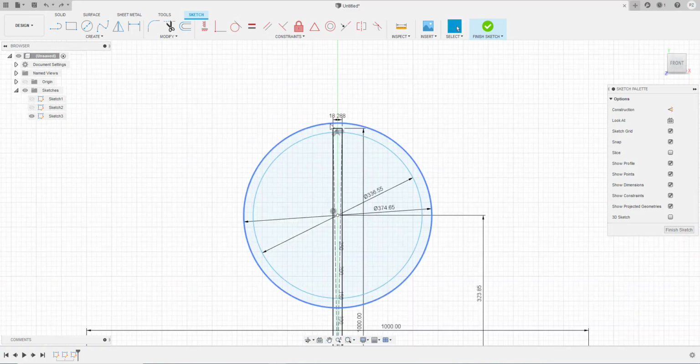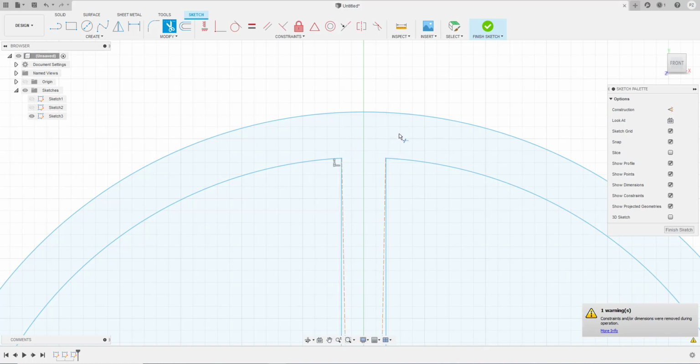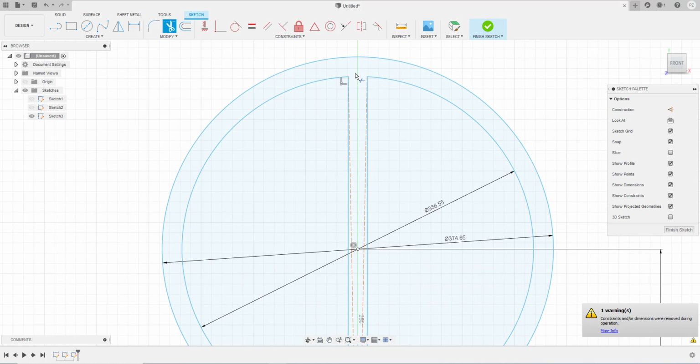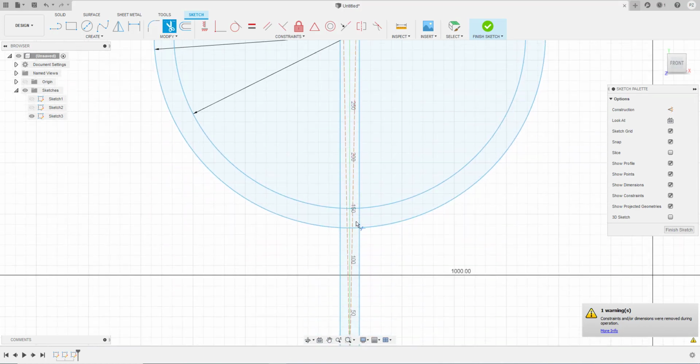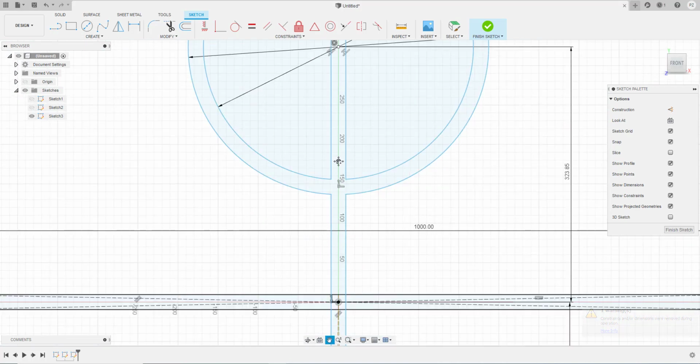Let's get rid of the lines first with the trim tool. So I'm going to select trim. I'm just going to kind of click on anything that's kind of interfering with the object. So I need a flowing space over here. I kind of cleared out the things on the top. So if I poured water from the top, it could go in from any direction. And I'm just going to go down to here, where if water was flowing in, it would stop at this wall. So I'm going to delete this wall. And I could even delete these lines. You don't need them anymore.